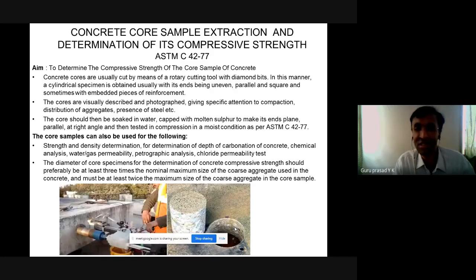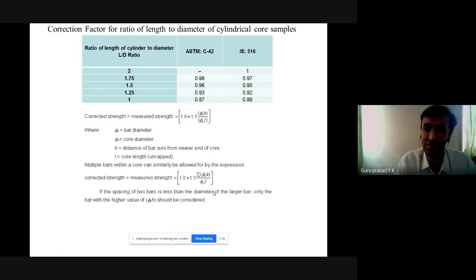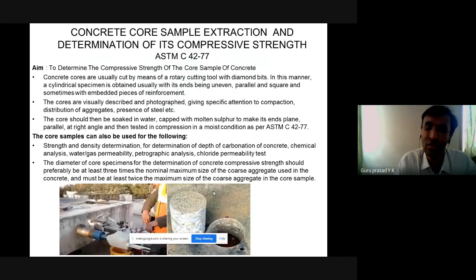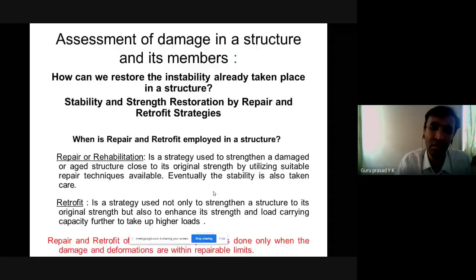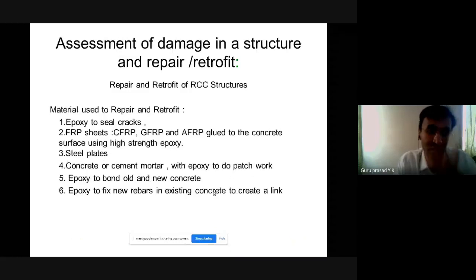A high strength cement based grout, or concrete grout, is used to fill that particular core. A high strength grout is used. Okay. So it should not be just left like that. That high strength grout should have a compressive strength higher than the compressive strength of that particular concrete also. So let me tell you that. I wanted to inform you that.